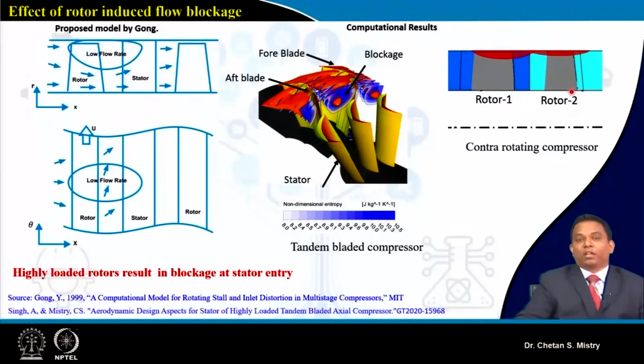And if you look, I am able to manage my flow and minimize the effect that happened because of growth of the boundary layer and growth of the tip leakage flow. So, according to our understanding, we need to move forward with this. This is also one of the advantages of using the counter rotating concept. As and when required, we will discuss the benefits of different kinds of configurations.